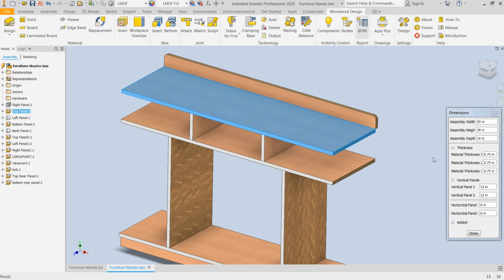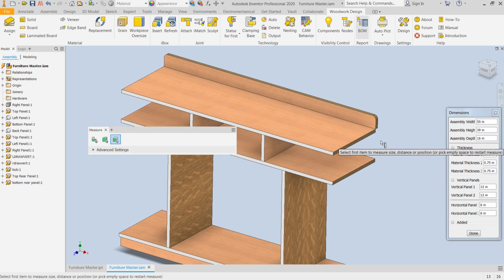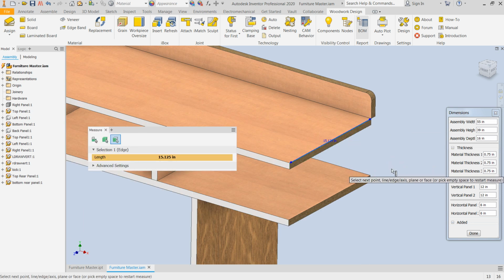So if I'm going to place a dado, a blind dado, I'm going to have to add material to this. And if I add material to it, then the bill of material, the cutlist, has to increase. Okay, 53.5 is our magic number. And the depth of this is exactly 15 1/8.